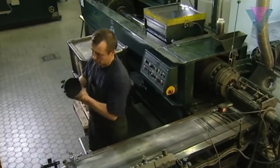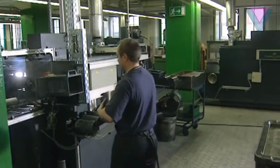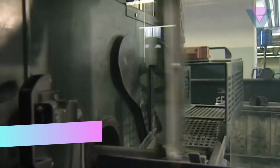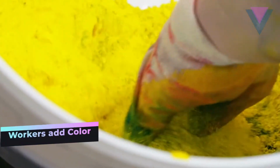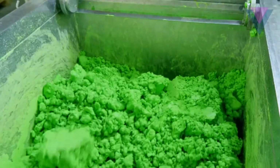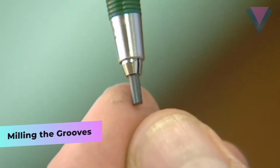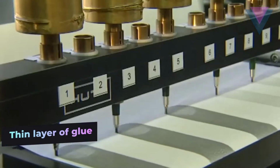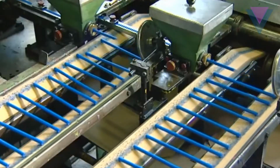The work continues as the lead is pressed with water to make a fine, soft paste. It is placed in a preheated oven of up to 1800 degrees Fahrenheit to help it dry and harden for efficient writing. For the colored pencils production line, the workers add colors into the graphite and clay mixing machine. Moreover, the pencil factory has fast machines that aid the speed of production. This is done by milling the grooves and applying a thin layer of glue to them. The groover machine cuts the slats into 8, and there you have 8 pencils.